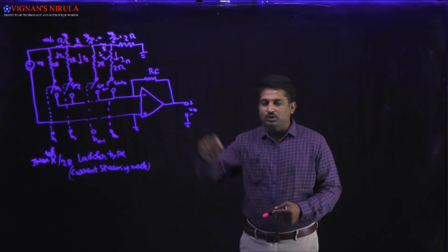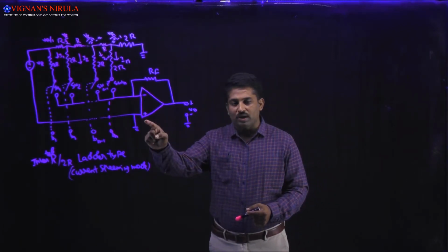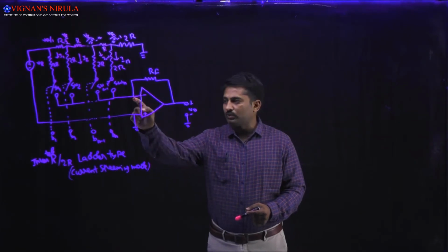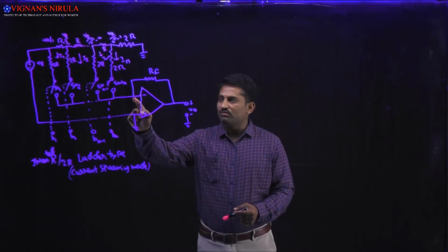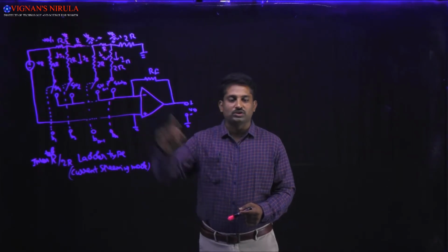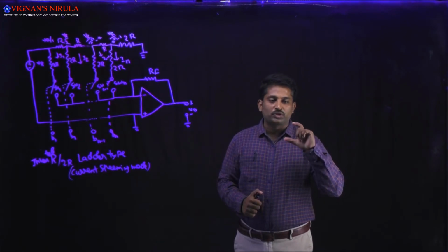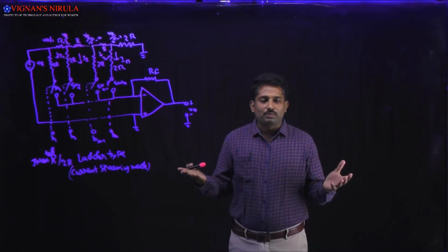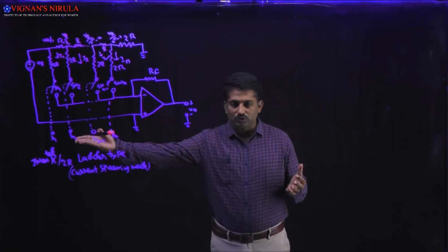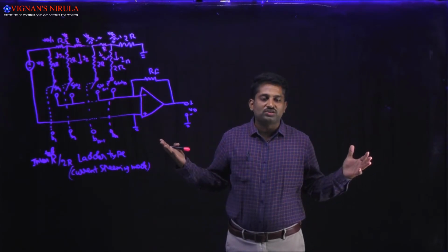If you observe the circuit diagram, the non-inverting input terminal of an op-amp is connected to ground. According to the virtual ground concept, the potential at the inverting input terminal of an op-amp is also at ground potential. So both switch positions are at the same potential. Whatever binary input you apply at the switches, we generate a constant current.